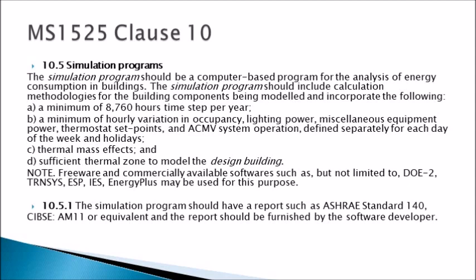And the software should also be able to reflect thermal mass effects. Thermal mass effect is the ability of the building envelope to retain heat and re-release the heat later. This is especially important in our climate, where during the day, heavy mass construction will absorb the heat from the sun, but it will release the heat slowly during the night.